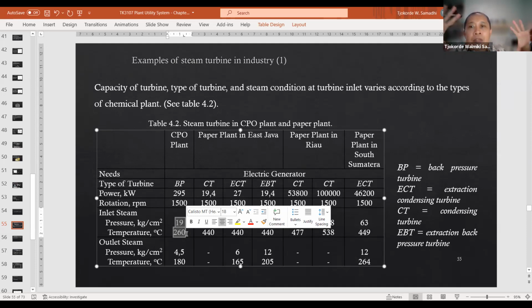So throughout our entire steam system, if the steam turbine has the highest steam pressure and temperature, then the steam turbine will determine the overall condition of the boiler output. It will determine the boiler pressure and the boiler temperature, right? I think that makes sense. Now, that may not be true if you have any other unit within your steam system that requires steam at an even higher pressure and or temperature compared to your steam turbine.